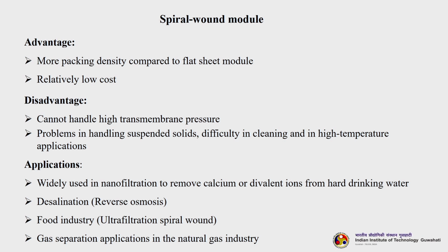A disadvantage is that it cannot handle high transmembrane pressure, because if the transmembrane pressure becomes high, pressure will build up inside the membrane module in such a way that it is not good for the separation, and you will not eventually get the targeted separation. Then another problem is handling suspended solids. It cannot handle a good amount of suspended solids, and there is difficulty in cleaning and in high temperature applications.